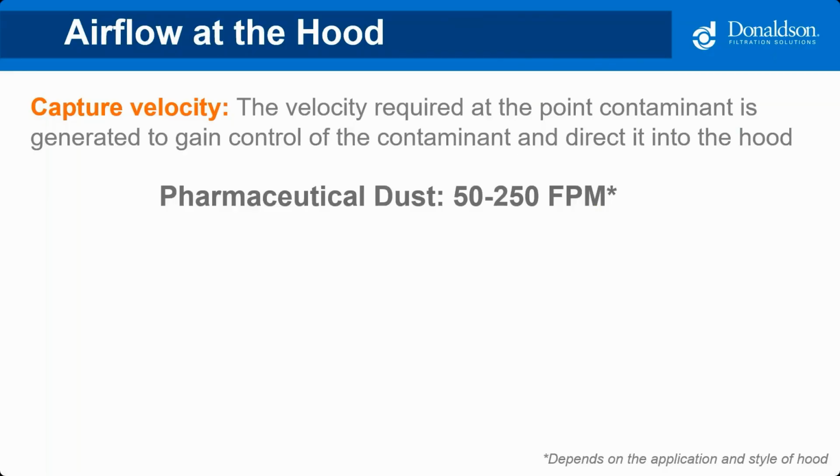When designing hoods, we want to avoid airflow extremes. Too much airflow at the hood or pickup point may mean you're picking up good product rather than just nuisance dust. And since more energy is required to move that airflow, it can lead to higher than expected operational costs. Insufficient airflow at the hood could require additional housekeeping measures to be implemented, and depending on the type of dust, may lead to an increased risk of exposure to potentially harmful dusts.